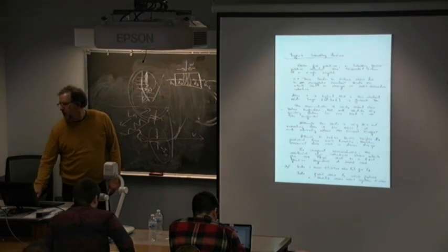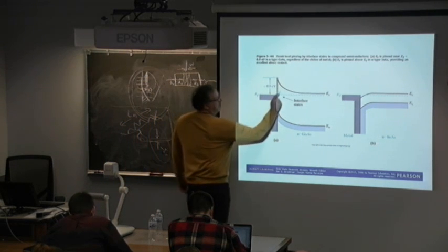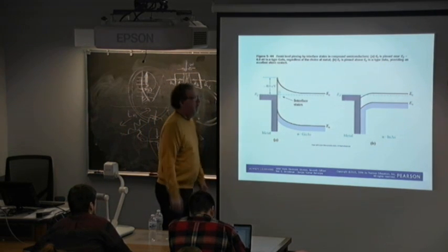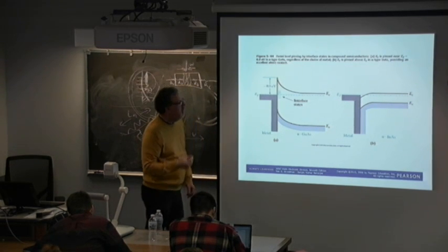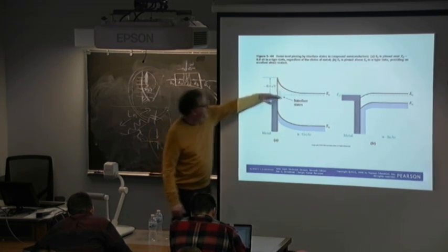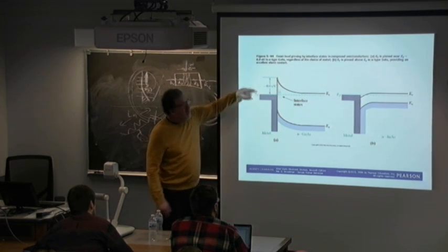In practical, real-world metal semiconductors, we actually get Fermi-level pinning, where you get traps and defects, and sometimes the density of states associated with that is so high that the Fermi level pierces that recombination, that trap level, and it pins the Fermi level.